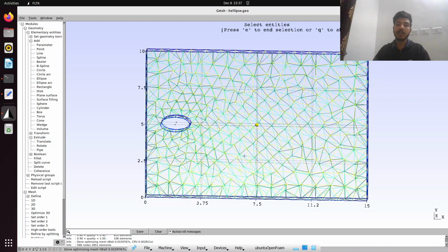But one thing we are missing over here is that this is a uniform mesh. If you have studied external flows during fluid mechanics, then you must know that there's boundary layer separation and the development of boundary layers occurring around the region of the obstacle, right? There are a lot of interactions and instabilities of the flow going on around here. So in order to get accurate values of our properties like velocity and pressure, we should have additional node points around this obstacle, right?